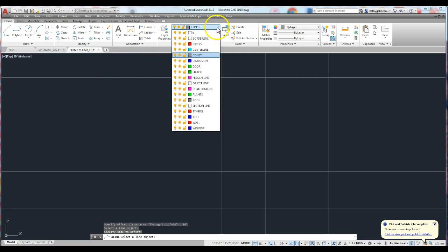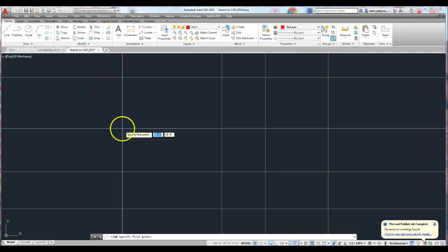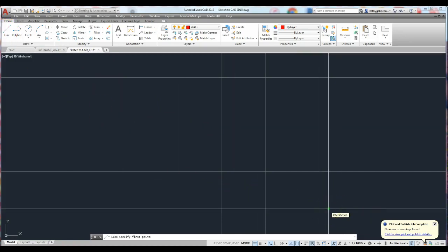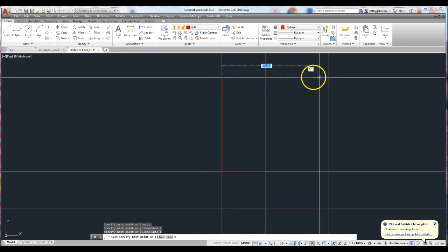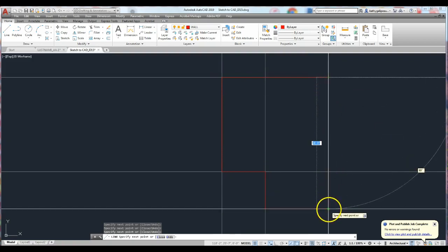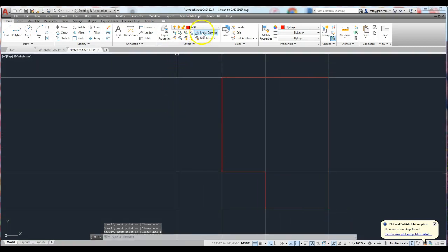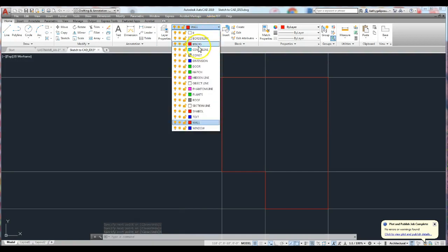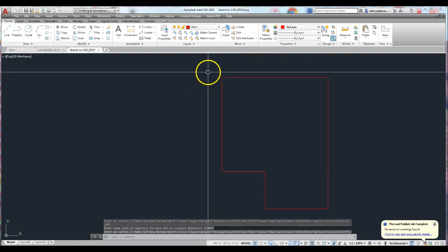I'm going to switch to the wall layer and start drawing my walls. Line command. Pardon me. I know that this is my bottom right-hand corner of my wall. I have my snap set, and I'm going to snap to all of these intersections. And I could close, or I could snap down to that bottom where I started. Enter. Let's turn off our construction lines so we can see better. So now I have the outline that quickly.